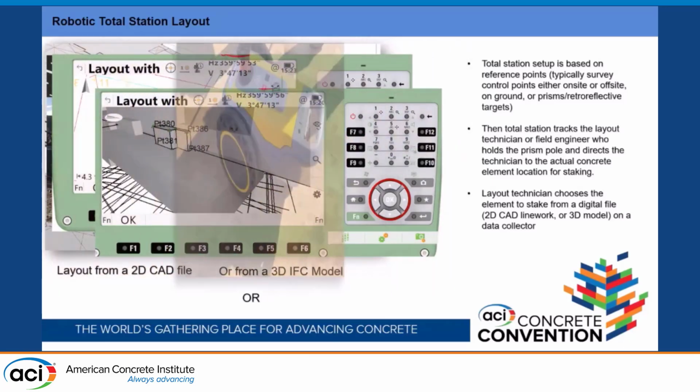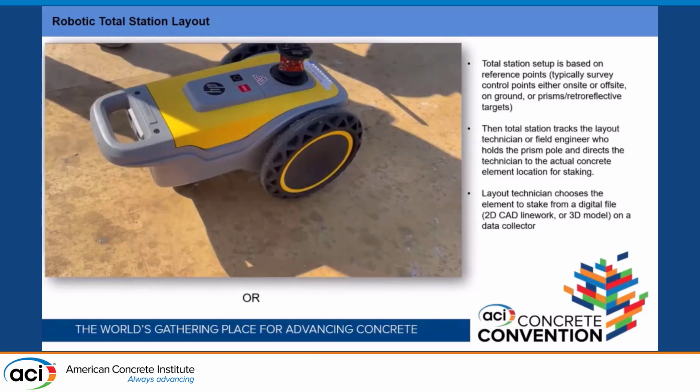Or nowadays, there's a little layout robot running around on job site. This layout robot has been around for probably almost 10 years, depending on the model. This is the one we did a demo of recently. The total station is tracking the little prism on top and guides the robot, and it prints a line onto the surface, either on the concrete slab or, in this case, the metal deck. So it limits the need for snapping lines or carpenters having to draw the lines. But I have more stories at the end of my presentation for this.